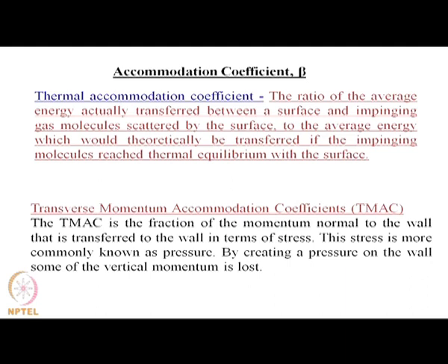When we talk about something similar to the thermal accommodation coefficient, there is something called the transverse momentum accommodation coefficient. It is the fraction of momentum normal to the wall which is transferred to the wall in terms of stress. The stress is more commonly known as pressure. By creating a pressure on the wall, some of the momentum is lost. So this TMAC, the transverse momentum accommodation coefficient, takes into account this loss of momentum of a molecule when it